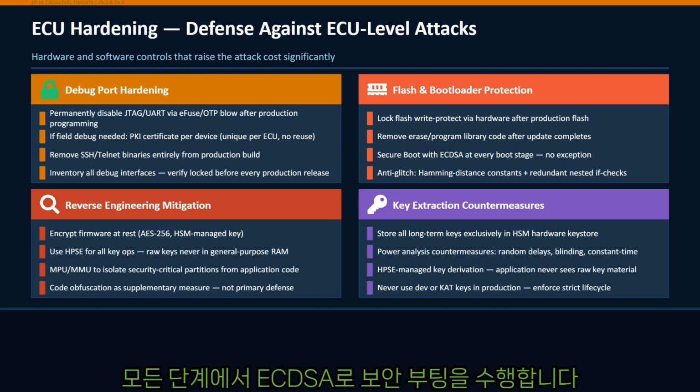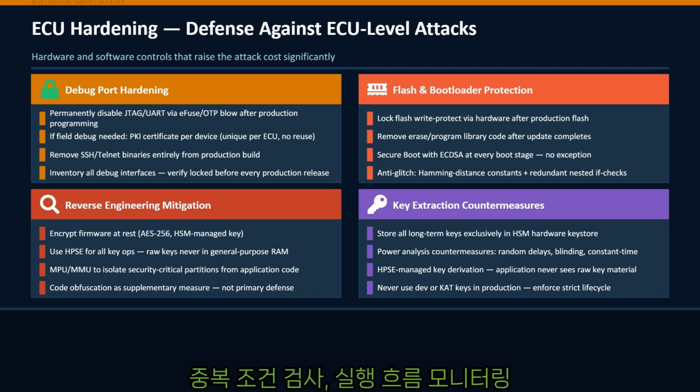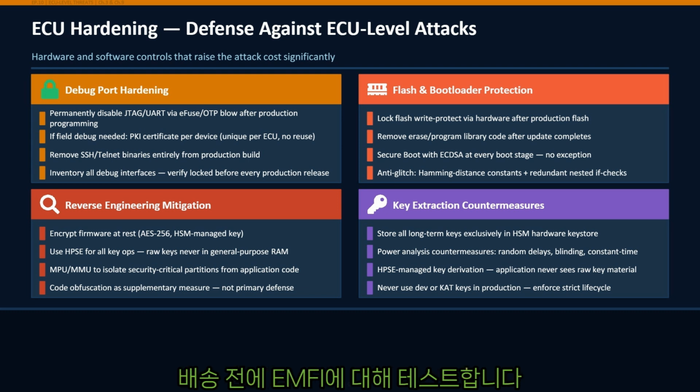Secure boot with ECDSA at every stage. Anti-glitch coding: Hamming distance constants, redundant conditional checks, execution flow monitoring. Test against EMFI before shipping.